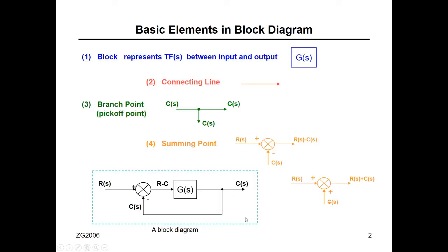What you see here is a typical control system. This is a block diagram of a typical control system. This is what we call the reference input. This is the output. This is the feed forward transfer function. This is the feedback. This is the summing point, plus, negative. This signal is the error, because it's the difference between what I want, the input, minus what I get, the output. We're going to talk about this more in detail, inshallah, when we come to chapter 10, control systems.